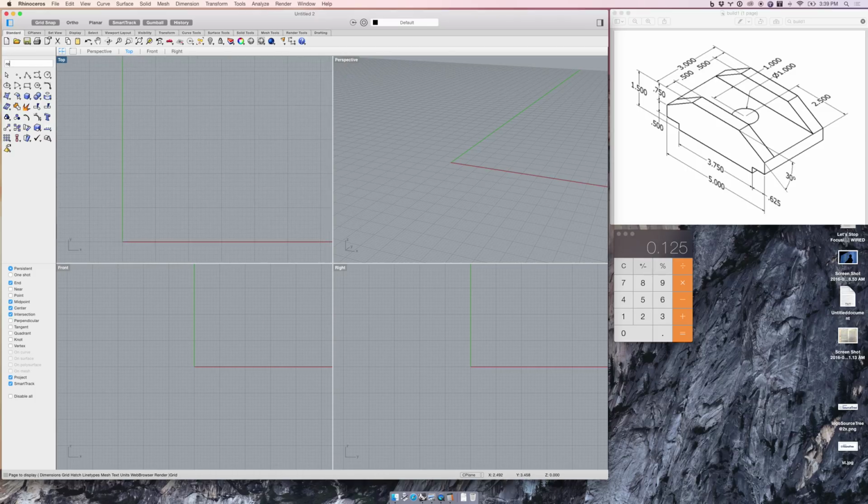And I like to just type. So on my keyboard, I'm typing rectangle. And then I want to make sure that my O snaps are on. I don't think I need end or midpoint or center right now, but intersection is pretty helpful. So I'm going to grab that corner and I'm going to go over 3 inches and I'm going to go up 5. And you'll notice also this keeps track of where your cursor is. So when I started here, it was 0, 0, and it goes up to this corner, which is 3 and 5. So I have my base rectangle.